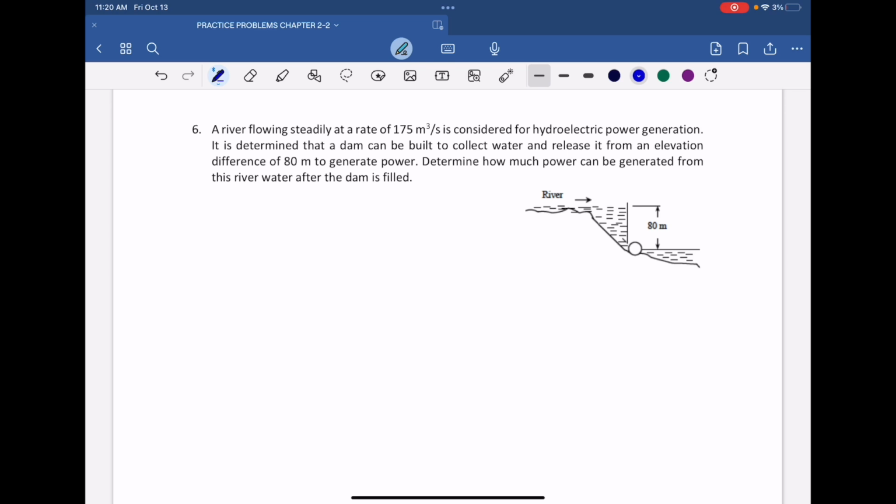So similar to what we have done before, we are calculating the mechanical energy, which should be equal to its potential energy, because mechanical energy again is equal to flow energy, kinetic and potential energies, but no information is given to us about the flow energy and the kinetic energy. So those terms should be insignificant, because the main contributor to the power generation should be the potential energy of that river. So this is again g times z or h, and then